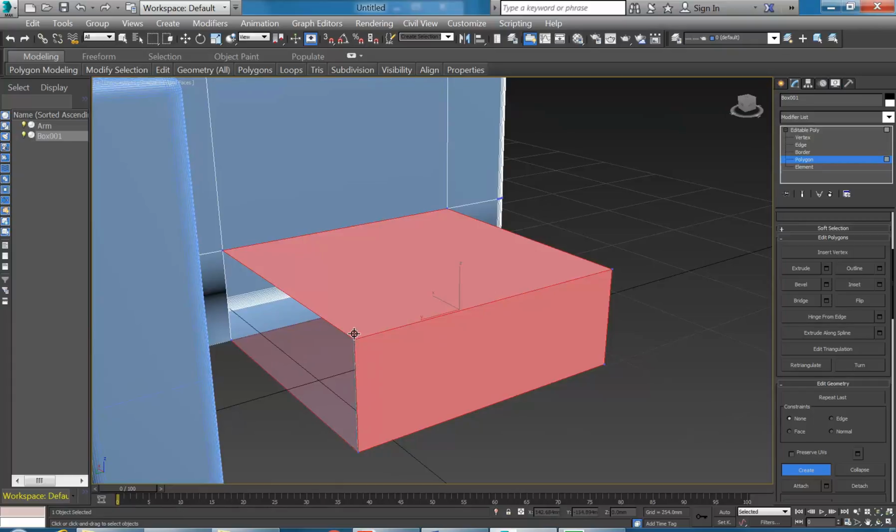And does anyone know the reason that you might need to draw these clockwise instead of anti-clockwise? What are the possibilities if we're just creating an abstract face or plane in a 3D environment? Or maybe have a look at the faces, what's happening with that face on the base as opposed to the one on the top. Notice how they look different? Pretty much, yep. So this one is greyed out, and that's telling us it's back facing. In other words, it's facing away from us.